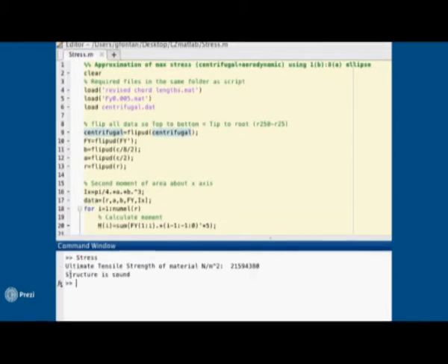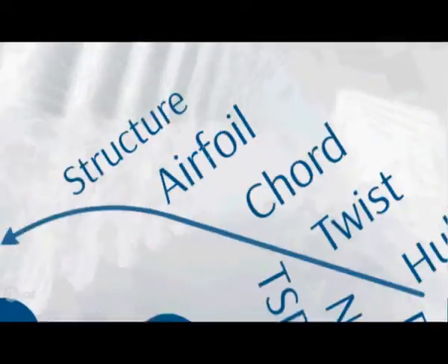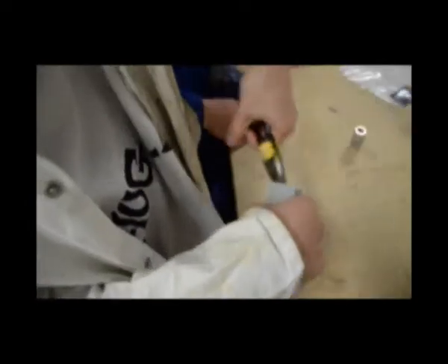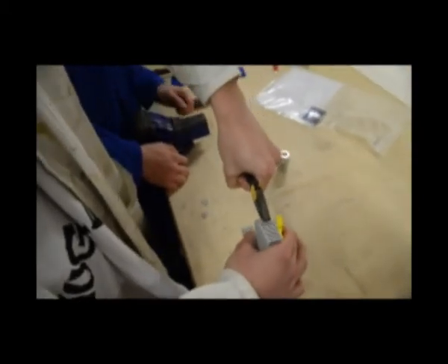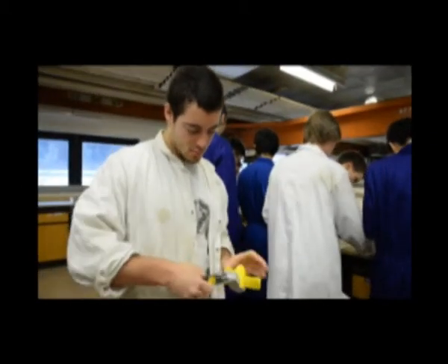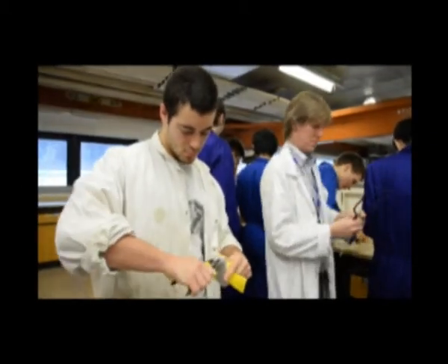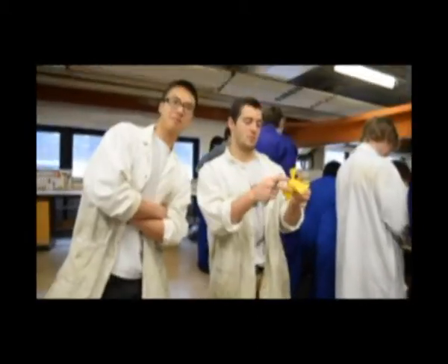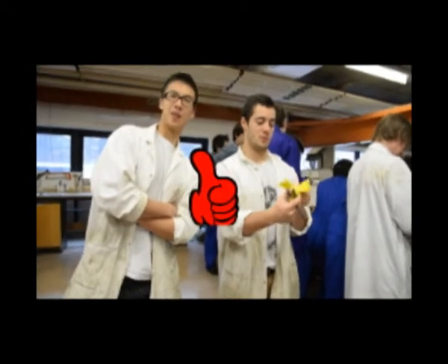The blades and nose cone in the turbine are manufactured using a rapid prototyping process known as fusion deposition modeling. This method is used as it is good for producing rigid functional models from ABS plastic, which can be machined, sanded, and tested. Due to the size restrictions of the rapid prototyping machine, the nose cone and blades were printed separately and thus need to be glued together.